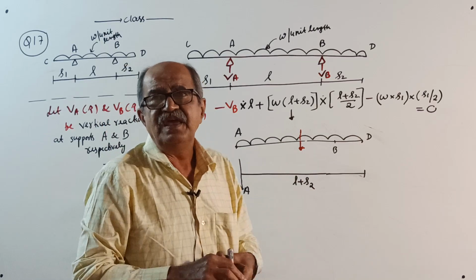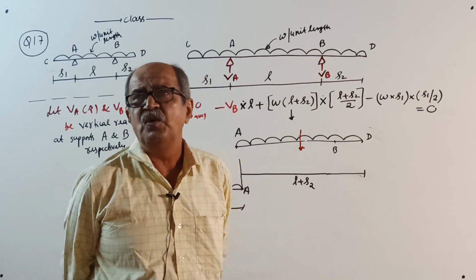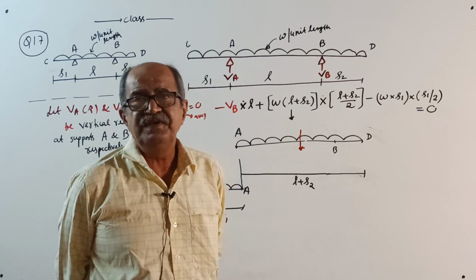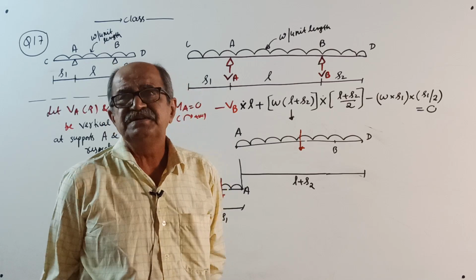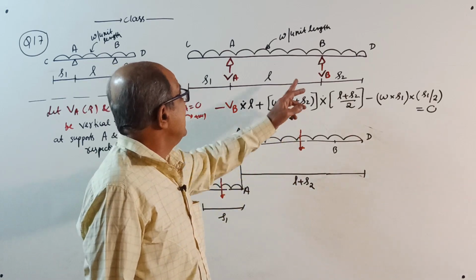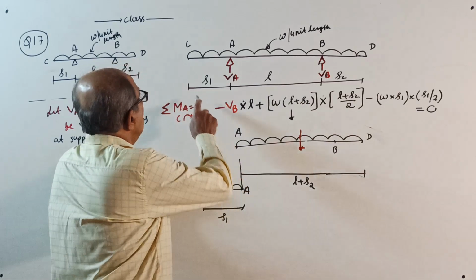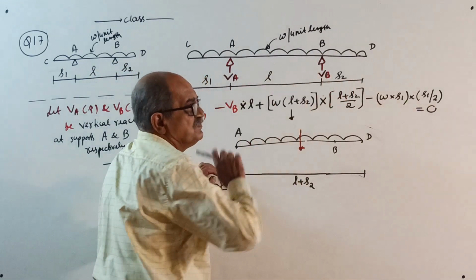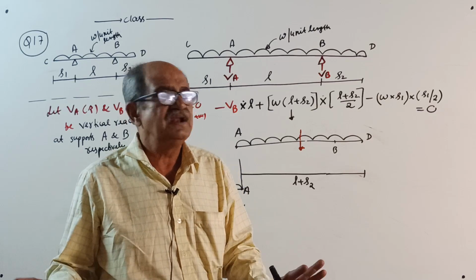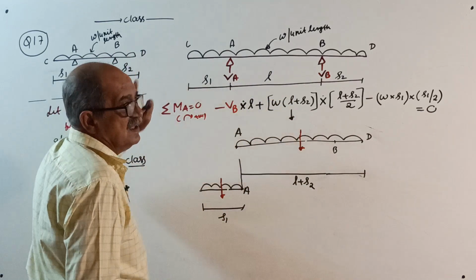And one more thing, for a simply supported beam, we consider central point load, eccentric point load, couple, and uniformly varying load, different cases, same for cantilever. Such standard cases are not discussed for overhanging beams. For overhanging beams, only one standard case is there, that is when there is UDL over the entire span. If other loading is given, you solve like a normal question. Therefore I have given only UDL here.